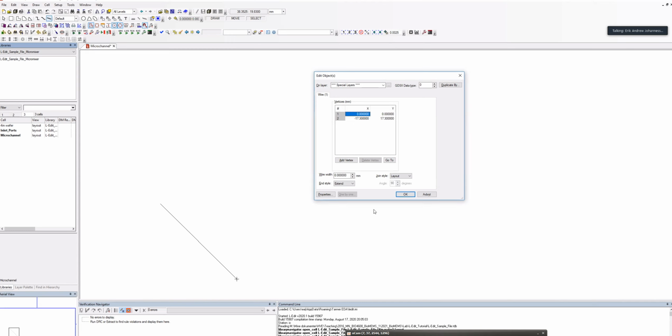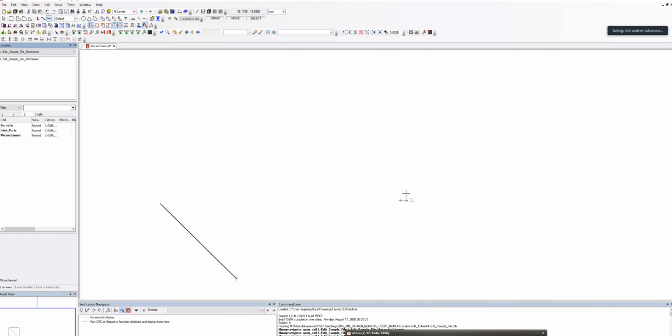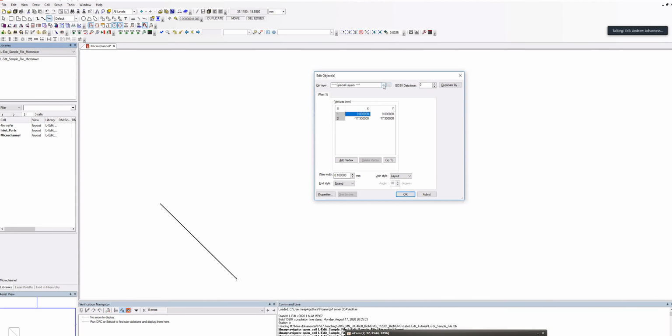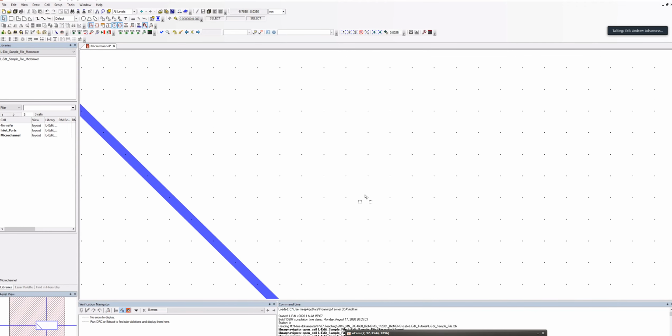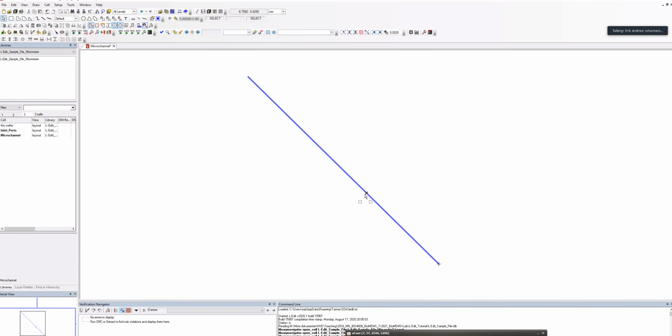But in order to go from a wire to a channel, you need to add a width, and this is given in millimeters. So if it's 100 microns, it's 0.1 millimeter. If you would like to use the same layer as you did for the inlet, then you choose layer 1. Okay, hang on, to go back into arrow mode here. You have a wire that is 100 microns wide and 3 centimeters long, and so on.